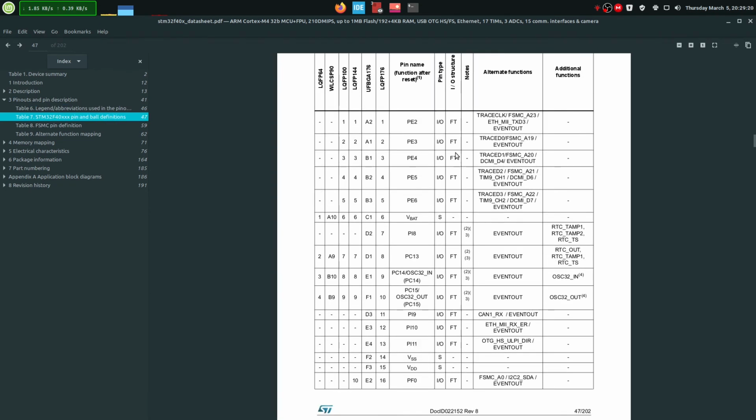So this is the table. It starts with the pins over here, and here there's the pin name. The name always starts with the port, and A, B, C, D, E, depending on how big the processor is and how many GPIO cells it has, different ports, and each port is just a bunch of pins. In this case, each port commands 16 pins. So you have 16 pins on A, B, C, D, E. I don't know if all are populated, but this is how it usually goes.